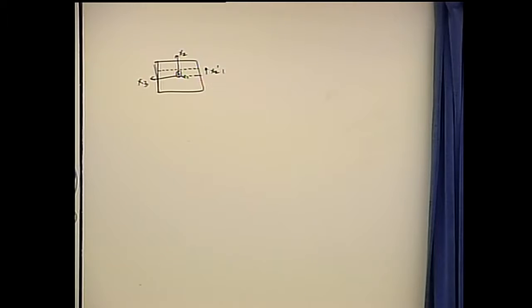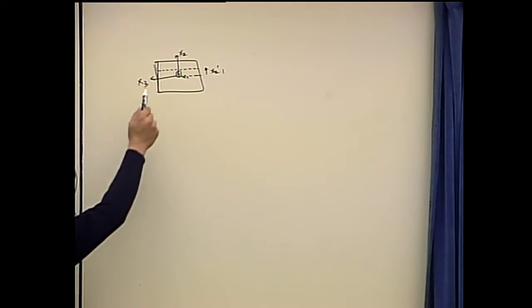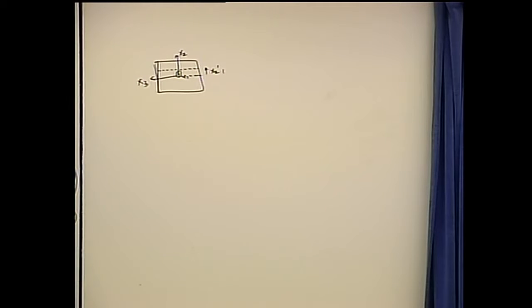What would happen if the axial loads were not there? What would happen to this neutral axis if the axial forces were not there? Yeah. The neutral axis would be on the axis of symmetry, on the x3. So the neutral axis would be parallel to x3 and it would be passing through the centroid. Can the neutral axis go outside the cross section? It can go outside the cross section. If the axial loads are too high, this line would keep moving further away. So this axis will no longer be in the section.